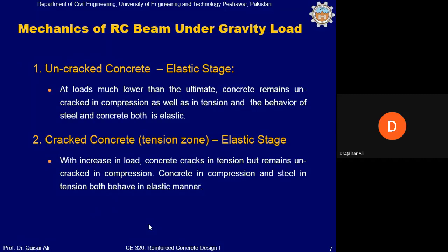You saw that the beam is bending between the two supports. You know the behavior of the beam in bending: the bottom fibers elongate and the top fibers shorten. So at the same time, simultaneously, in the top portion of the beam the beam is being compressed, and the lower part is being elongated. When stresses exist in a member in this combination, we call them flexure stresses. Because flexure stresses are produced due to bending, we also call them bending stresses.